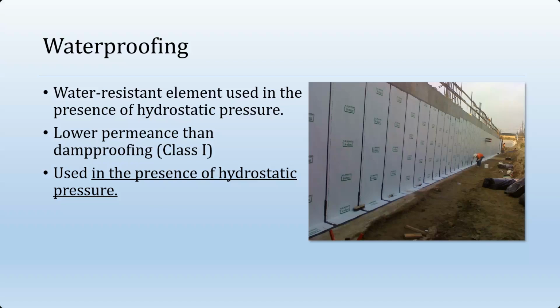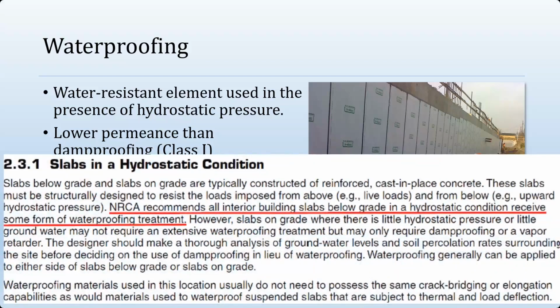Getting that close, you're likely going to be in positive hydrostatic conditions. So all 5 sides of the building's foundation were waterproofed, and a drain tile system was also incorporated. It's an interesting aspect. Now, there are also other references to where waterproofing should be used.